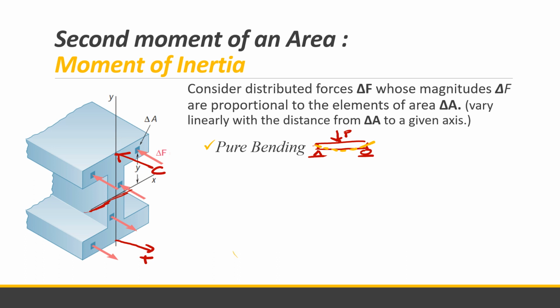So if you cut the section at the middle, for example a rectangular beam, the forces acting on this cross section will have a resultant of a compressive force at the top and a tensile force at the bottom.